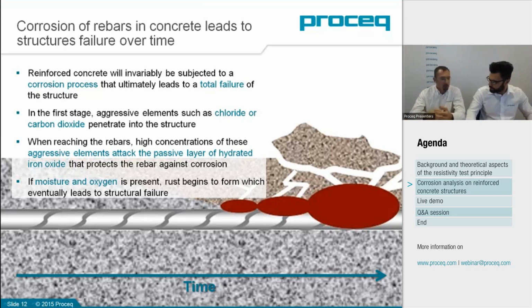That's where cracking or spalling will occur, and then the aggressive agents will have more ease of access to the steel. So it's a sort of accelerated exponential curve, which reminds us that when we see the damage, it's too late. That is the general criteria before going into chemical details.